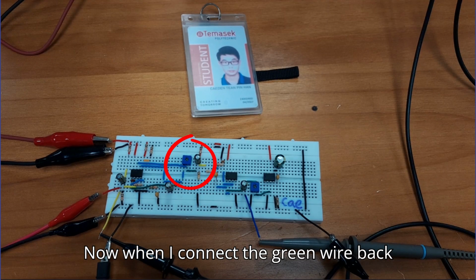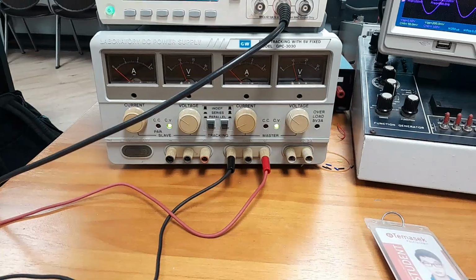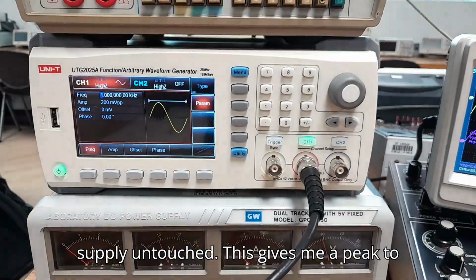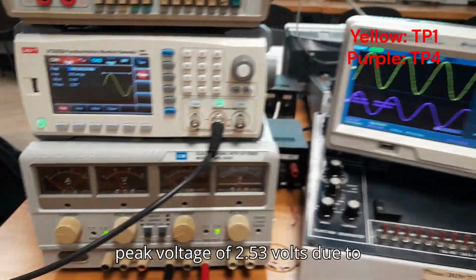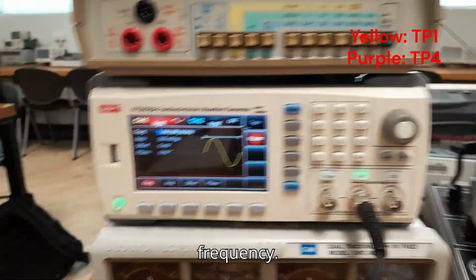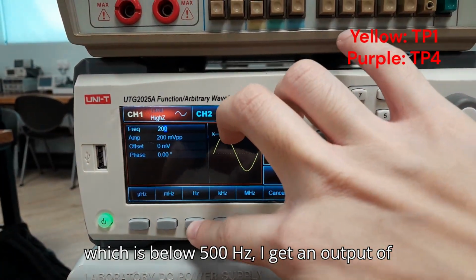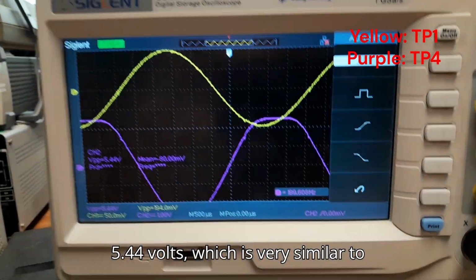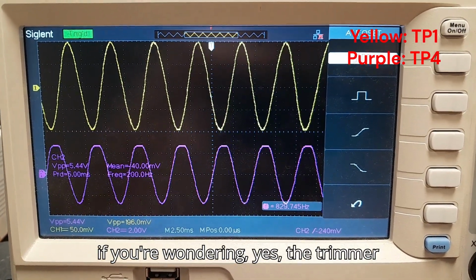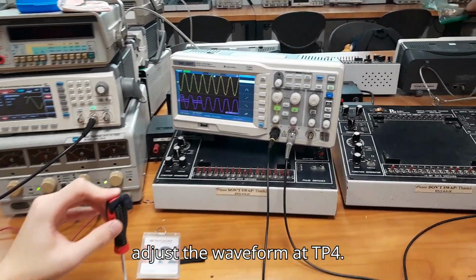Now, when I connect the green wire back and connect the second oscilloscope cable to TP4, I use a 1 kHz, 200 mV peak-to-peak sine wave for the function generator and keep the DC power supply untouched. This gives me a peak-to-peak voltage of 2.53 volts, due to the fact that around 1 kHz is the cutoff frequency. After changing the frequency to 200 Hz, which is below 500 Hz, I get an output of 5.44 volts, which is very similar to the output voltage we got at stage 2 before saturation. So if you're wondering, yes, the trimmer from stage 2 will also be able to adjust the waveform at TP4.